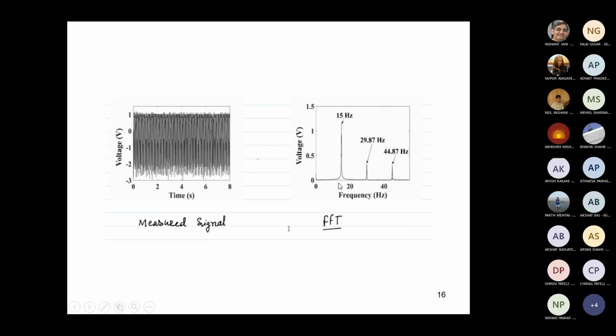And how do I identify the fundamental frequency? Because at this particular frequency, the amplitude goes to a peak value. It shows this sharp peak. So I can identify three natural frequencies for this system when I analyze it from 0 to 50.